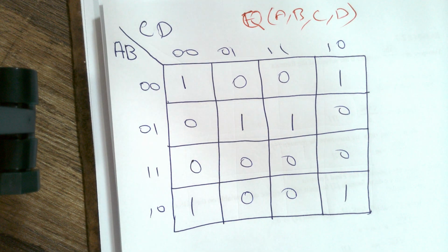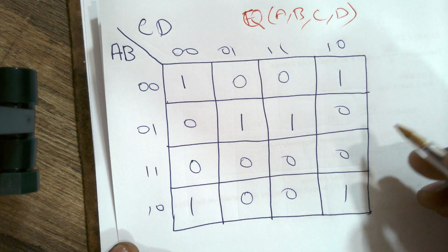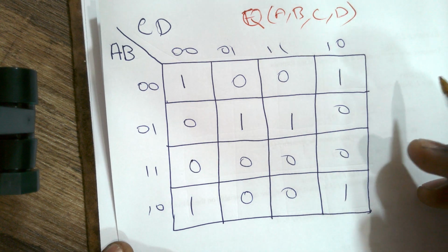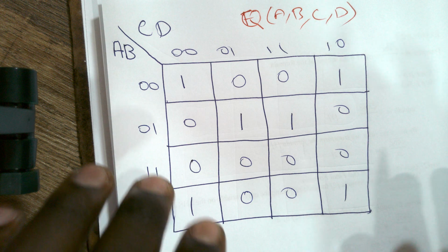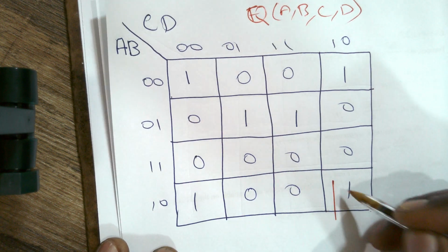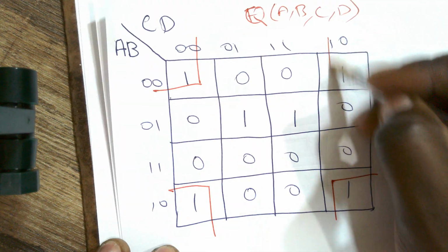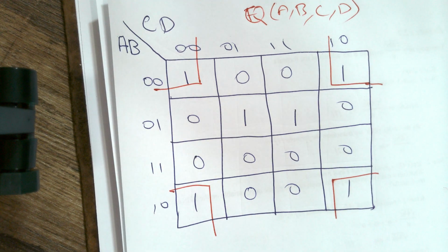So first thing, let's get the biggest or largest circles of ones and the least amount of them. The first thing you have to realize, I am seeing 4 ones in one circle here. That is because the corners actually wrap around, they're actually in one square, right? So this, and this is one square or circle with 4 ones.